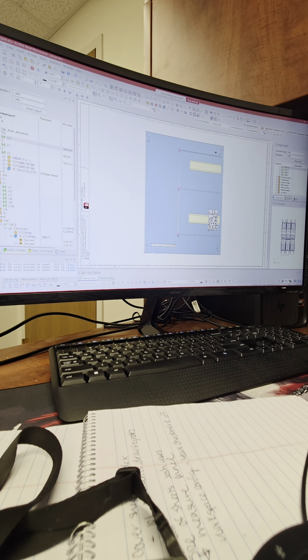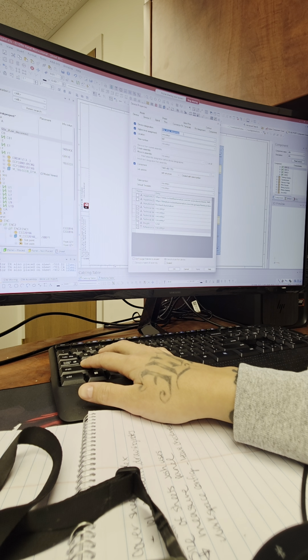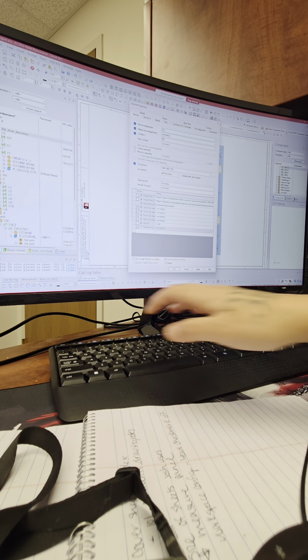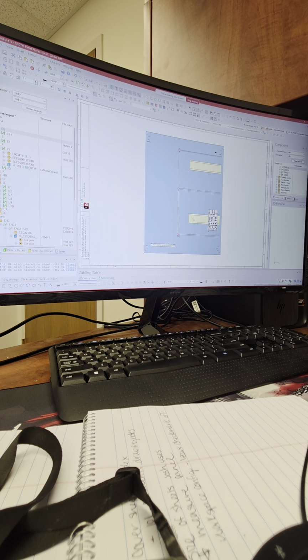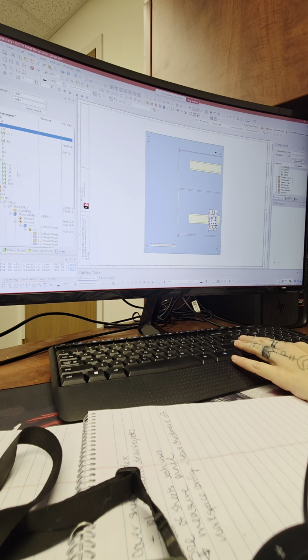Same thing with the 16 amp fuse disconnect. Let's expand that one. So fuse disconnect. I don't know what this might be. Let's just call this F1 for sake of missing description right now. All right, click OK. Looks like there's another one, so I'll just call it F2 for lack of better references. All right, that looks more proper. So take this CB1, circuit breaker, and let's drag and drop it so we have all our parts on the mounting plate before we close out here for the day.